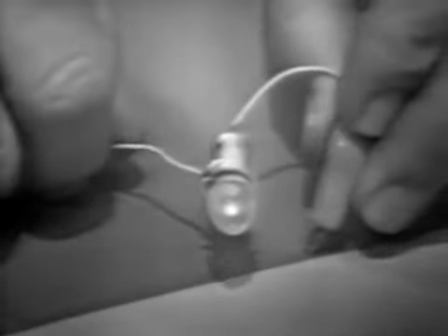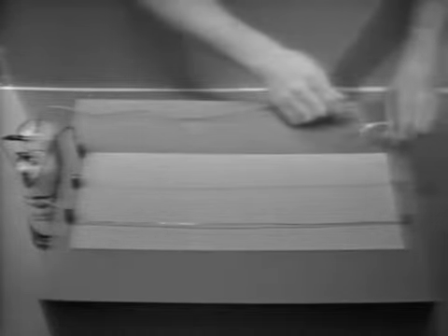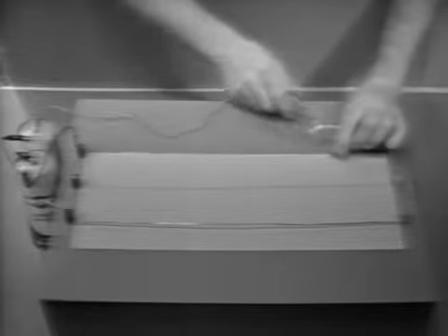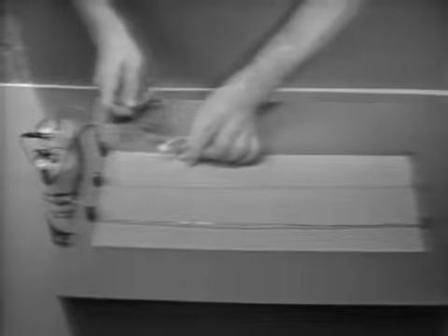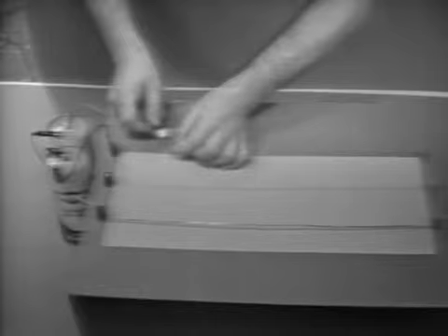Well, let's go on down to the end of the wire. Watch the bulb. As I decrease length, I decrease resistance because the bulb is glowing more. Well, this is pretty obvious. Let's take a look at it. When I had the bulb over here, the electrons had to travel the full length of this resistance material. So it's only natural that it's going to encounter more opposition. But as I decreased the length, I decreased resistance, and the bulb glows brighter. Then length is definitely a factor that determines resistance.